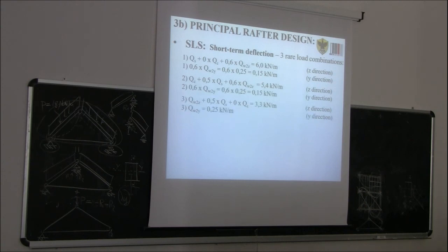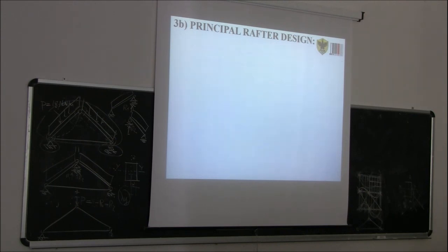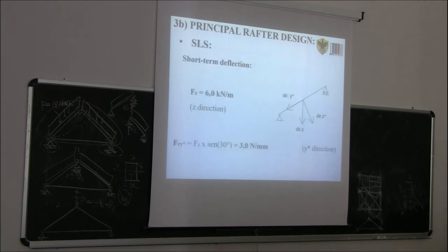If we replace the variables with the numbers, we find this value that you can find here. If you look at the highest value, it's by far the first one. So load combination 1 is the one having the snow as the basic variable load, and only 60% of the wind. Strictly speaking, there will be a component along Z, and also a component along Y, but the component along Y is very small. So those are the 2 components.